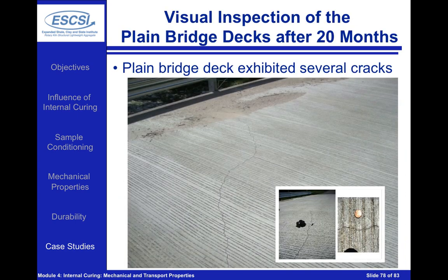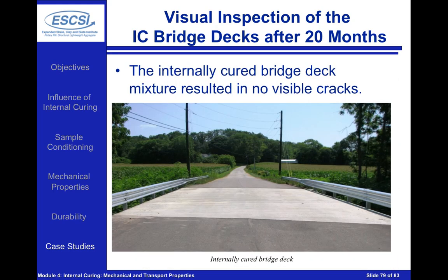But the main takeaway when we look at our internally cured concretes is we're going to have fewer cracks in the overall system. So we're going to be reducing the potential for cracking. This is a picture taken from one of those Bloomington projects. Here you can see the plain concrete where several cracks formed, 3 cracks that had formed and were monitored after 20 months, where the internally cured concrete showed no cracking after 20 months.